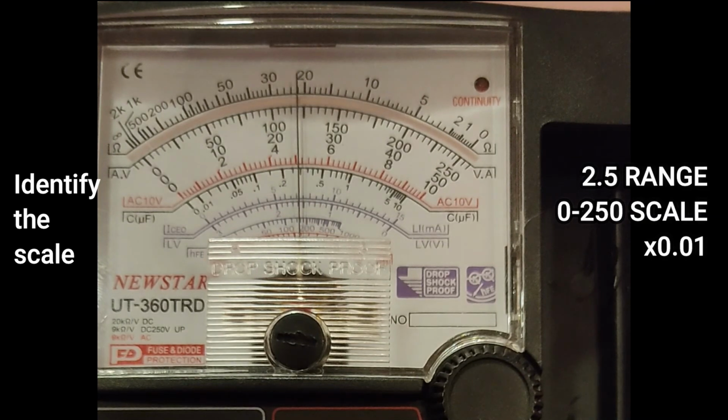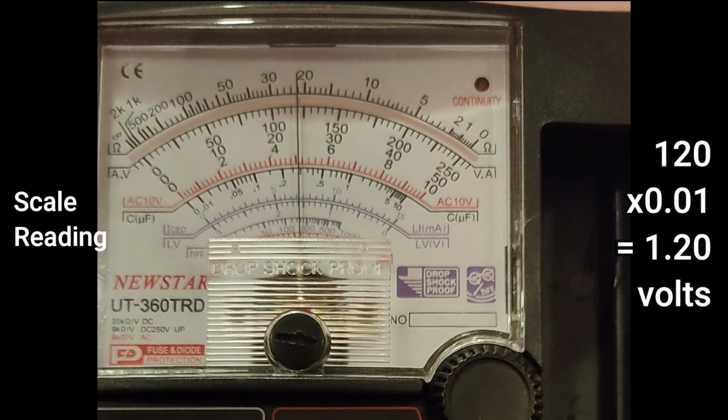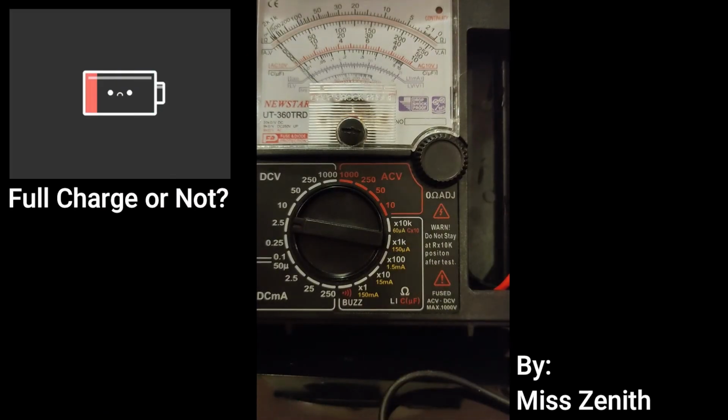The scale is 120, multiplied by 0.01, which is 1.2 or 1.20 volts, which means our battery is fully charged and ready to use. And that is how you test your battery at home.